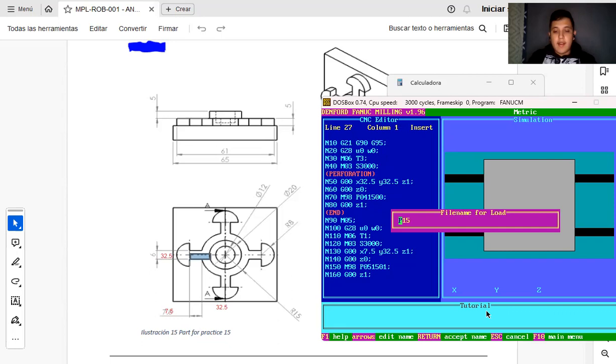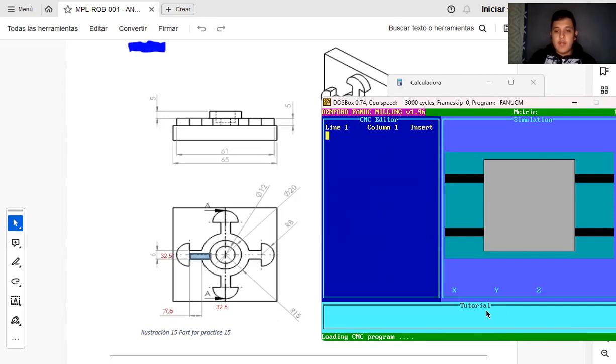I'm going to save. I'm going to go to this program. We're going to write G99, G minus 1, then G02 to move and do a circle around this. We're going to position it in the same place, and we're going to have a radius of 25 because it's the sum of the radius of the tool and the 10 millimeters.